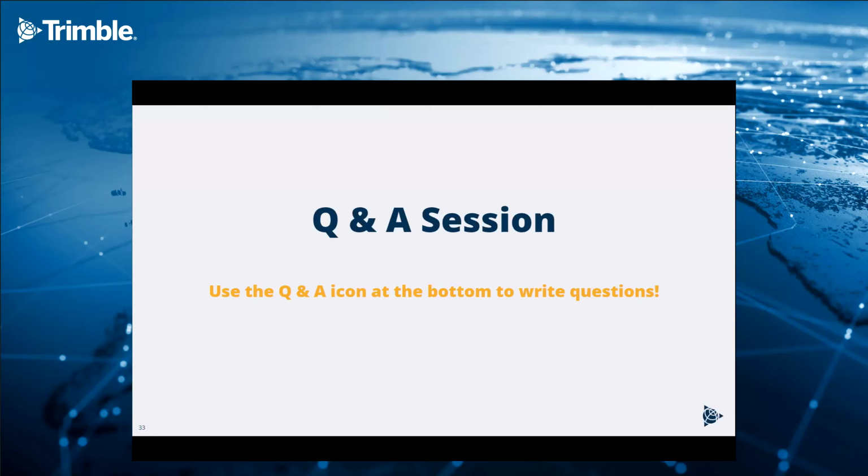But that's not the idea. The idea is not to process purely ground data. What we want to achieve here is processing kinematic data. For instance, if you have a base station where you want to have the coordinate, then you use that extra function, which is also based on RTX, as I said before. So you can simply upload your base station and say, please use RTX to survey in the base station coordinates, and it will do the job for that. But at the end, the idea is to merge the rover and the base, and you have some dynamic data. Okay.